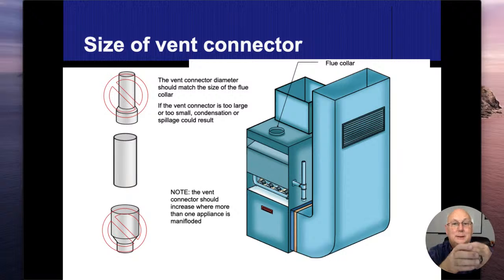And again, when I size it, it should be sized to the appliance. That opening that we're showing up here on the appliance right up above the dot, that is what the manufacturer says should be the vent connector. So in all reality, that's the size it should be. Again, we shouldn't get bigger, we shouldn't get smaller. All right. And this is for mid-efficiency furnaces.